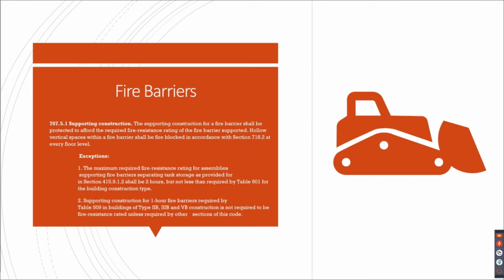And think about too, when you've got a fire barrier, we recently had a building where the construction type required a 1-hour floor assembly, but there was a use on the second floor that required a 2-hour fire barrier separation.